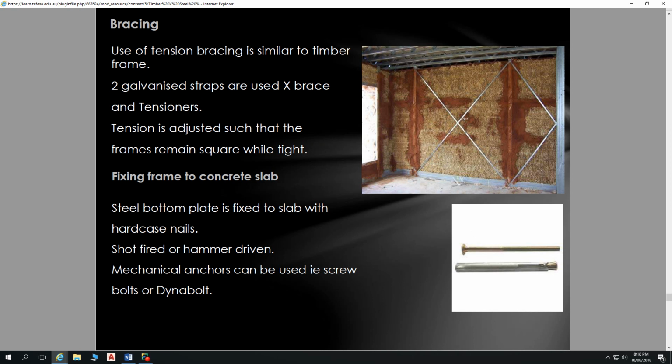And so also with bracing, a lot of the very similar technology as per our timber framing, but once again with the incorporation of a lot of trusses in the walls, they're self-bracing as well, and it minimises the need for additional bracing on those walls.